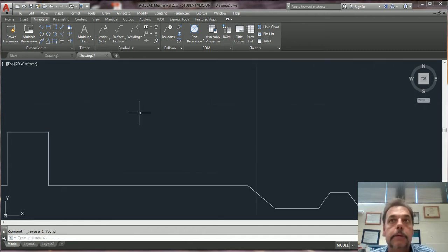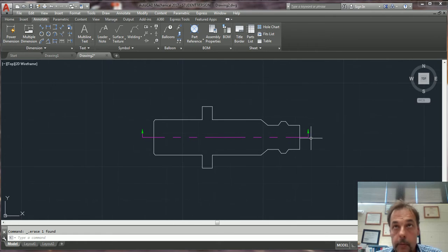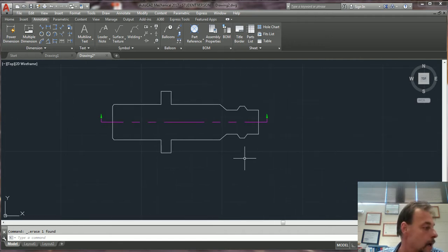All right, notice that the arrowheads are pointing upwards, which means it's like if somebody took a saw, cut through this part, and the section view then is going to go down here. So section view always goes opposite of the arrows. So it's going to go down here. So if I was running a section through this way and going to the left, then my section view would be over here, or my right side view.